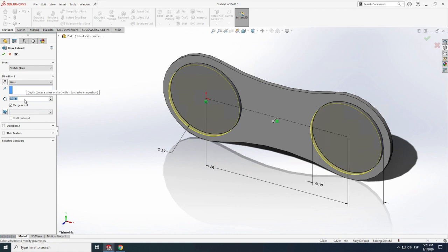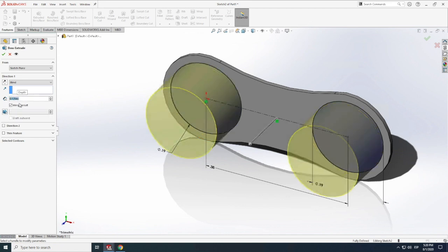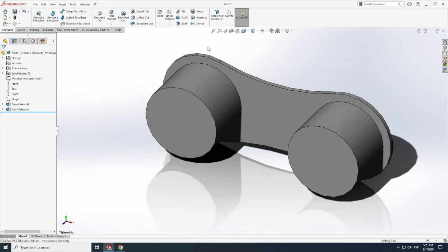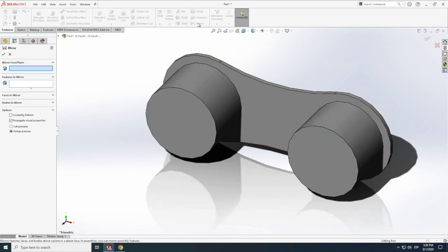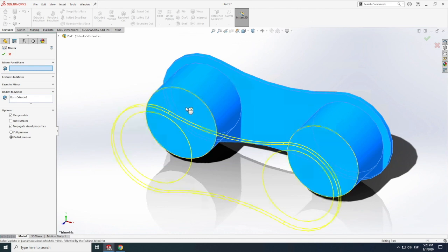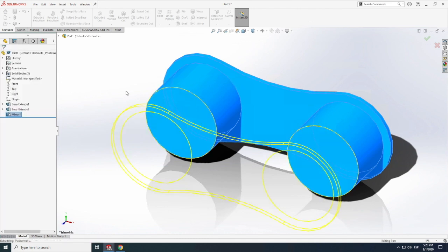So here's what we're gonna do. We're gonna extrude half of that. So that will be 2/16. So there we go. Why do I say this? Because we're gonna conveniently use the mirror. So we'll click. We're gonna mirror the whole body. We just click just in there. Mirror face is this one, and voila.